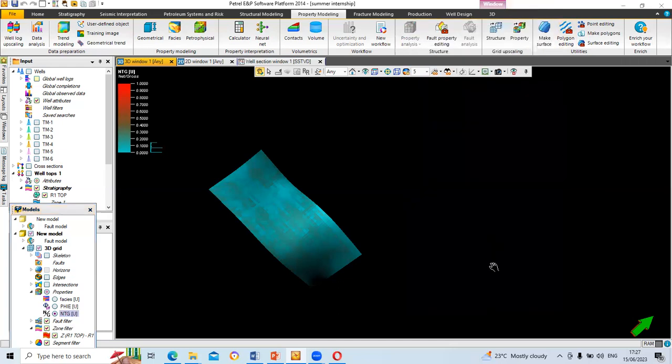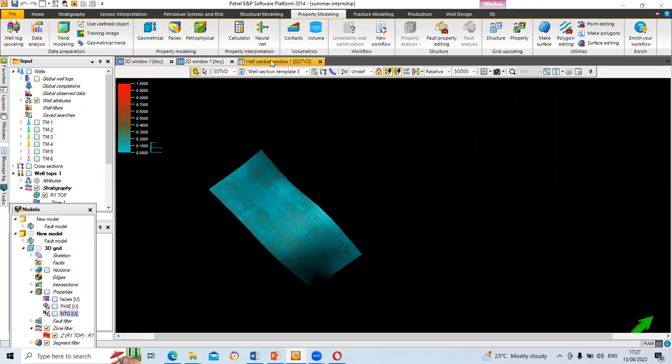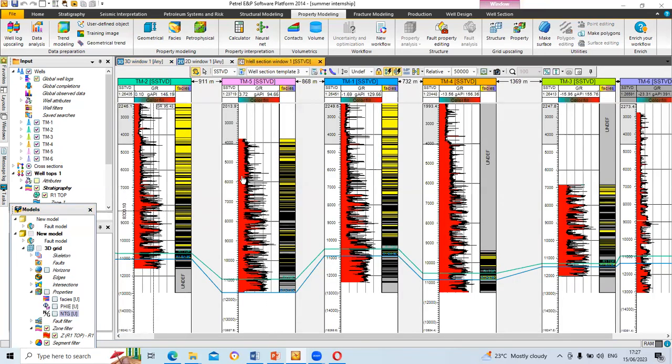You just go through it and see how. So for all of these structures, forget about this change that has taken place. This change is because of this parameter that I changed down here. It doesn't really matter. You can always change it back. So for all the correlated horizons that you're going to have, don't pay attention to this upper part. That is the Benin Formation. Mr. Zero already explained yesterday that we don't have reservoirs in the Benin Formation because what they have is fresh water. We have reservoirs in the Abada Formation, so we concentrate around this area. So you are going to pick these horizons, the various horizons, and then you go through the various processes of building those models.